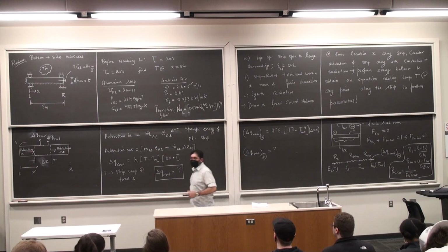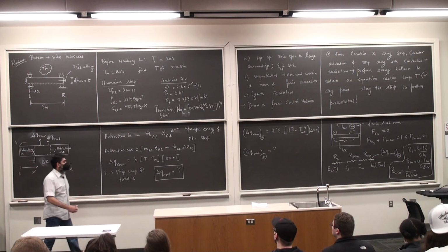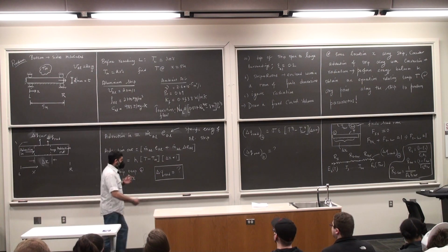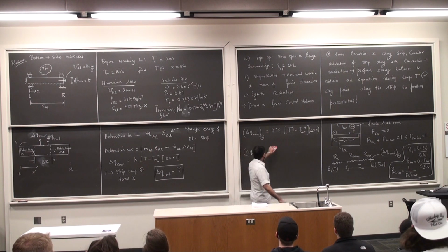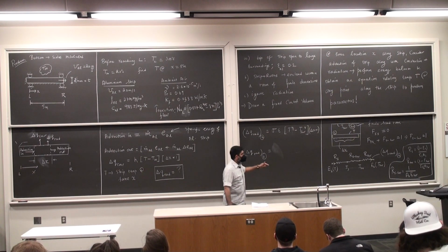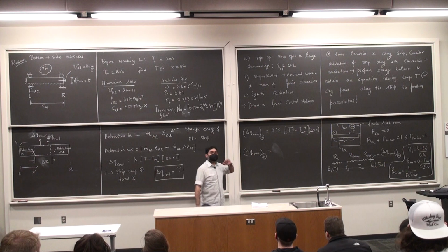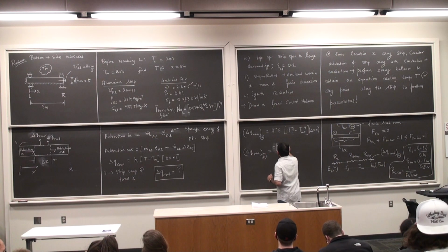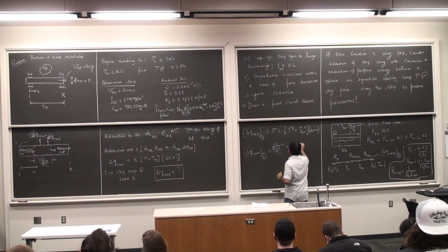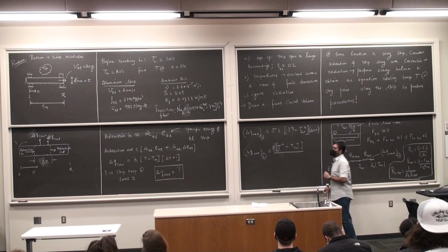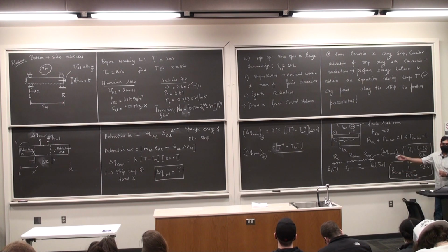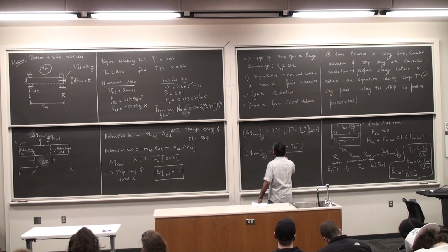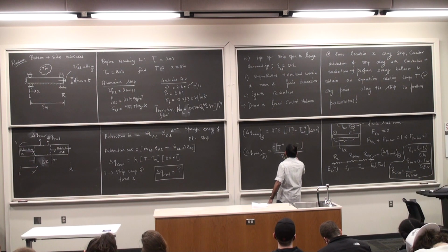Of course, I forgot to give you epsilon surrounding, but we can assume it's some kind of a value. Okay, so all of these will be given, and once I have everything, then here is the equation. T surrounding, those are the things that I'm interested in. So this is sigma T to the power 4 minus T surrounding to the power 4 divided by R total, right? This is nothing but a set of resistors in series. So this is R total, R_S, R surrounding, R_S surrounding.